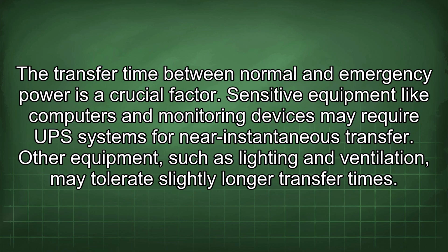The transfer time between normal and emergency power is a crucial factor. Sensitive equipment like computers and monitoring devices may require UPS systems for near instantaneous transfer. Other equipment, such as lighting and ventilation, may tolerate slightly longer transfer times.